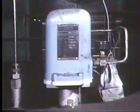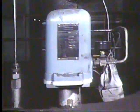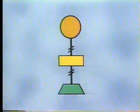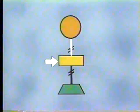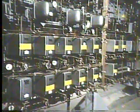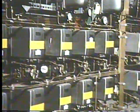The measuring function for pneumatic control systems is often performed by a transmitter that measures the value of a process variable and produces an output signal that represents this value. A process variable that is measured is sometimes called a monitored variable. The output signal from the transmitter is sent to an automatic signal processing instrument, which is represented by this rectangle. In pneumatic control systems, automatic signal processing is usually accomplished by a controller. A controller compares the signal from the transmitter to set point. If necessary, the controller produces a corrective output signal.